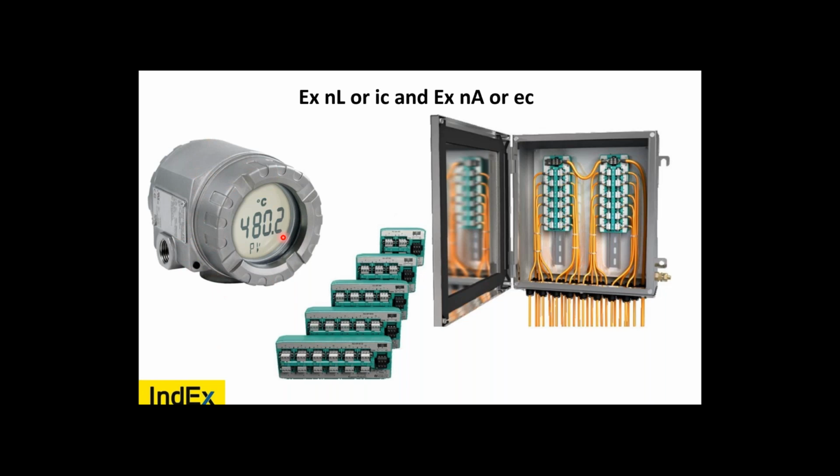But as the standards updated at different times, these internals changed to IC. IC, can it be outside? Inside of a control room, as long as it's IP20. But when it's outside in a hazardous area, zone 2 or anywhere, it has to be inside of an enclosure. So then you had them inside EXNA. Then as the standard updated in 2017 from edition 4 to edition 5, NA becomes EC.